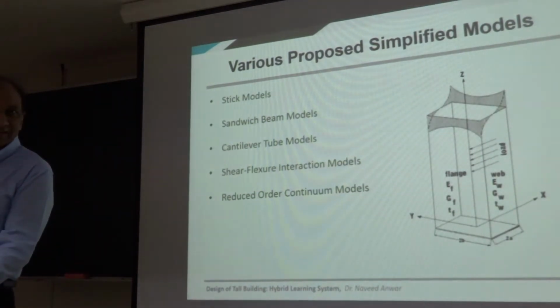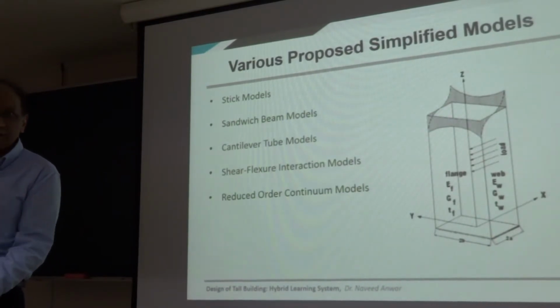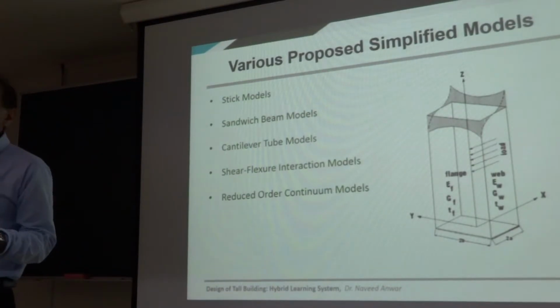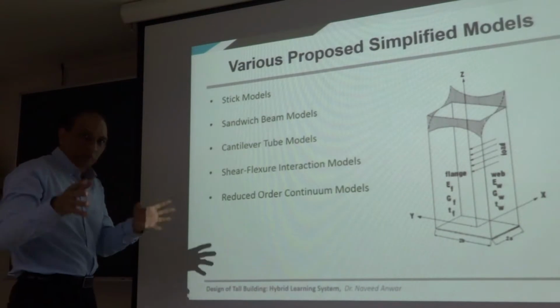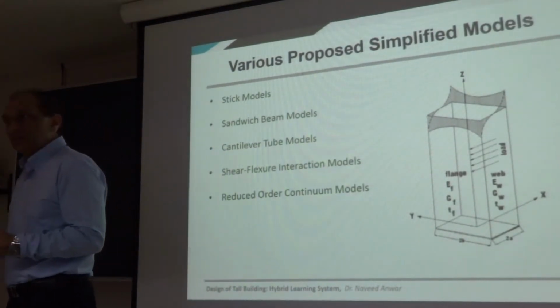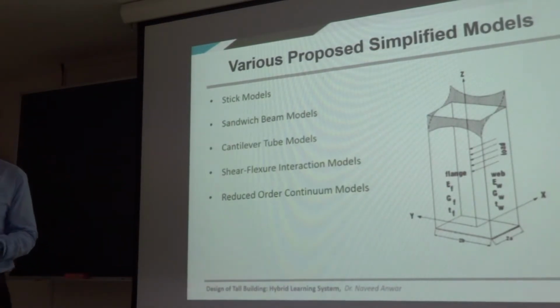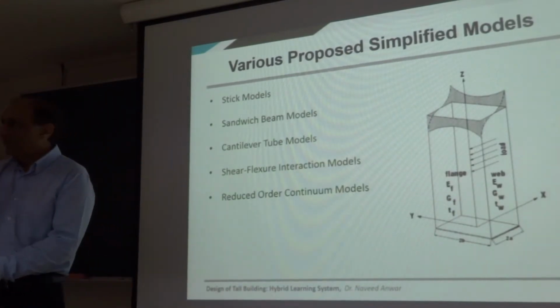And forget about the internal configuration of the stick for a minute, and you treat the whole building as a single stick, and then you do the calculation for that stick, total bending moment, total shear, right? As if there is no column inside, there's no shear wall inside. And based on those total forces, then you size various things. So don't worry about calculating the forces in individual members, because you may not even know those individual members yet. You'd rather do a calculation of the stick of the building and get the forces.